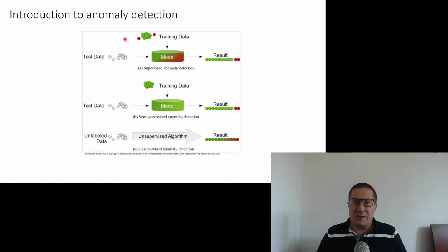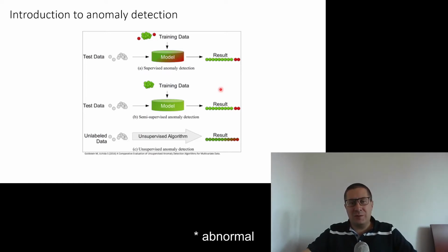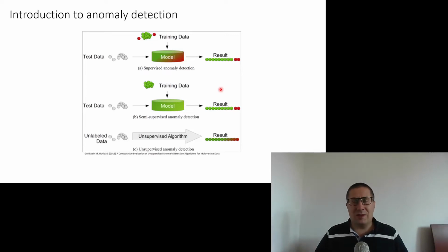In most cases, we have this case. So we have the data taken from the plant, and the majority of data, 99.9% of data, represents the normal behavior. If there was a failure, or something strange, usually there is some comment in the operator notebooks, in the dispatcher's notebooks. So we can identify points associated with normal behavior, or we can just assume that, well, if the majority of points, like 99.9%, come from the normal behavior, more or less all of them represent the normal process behavior.